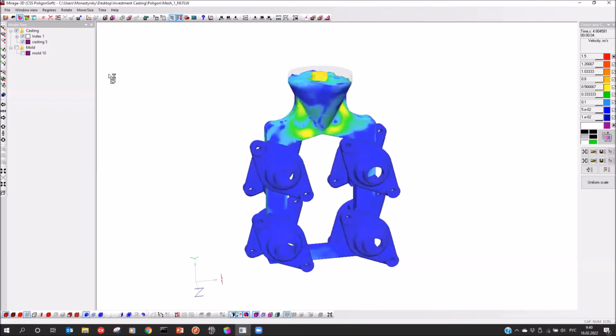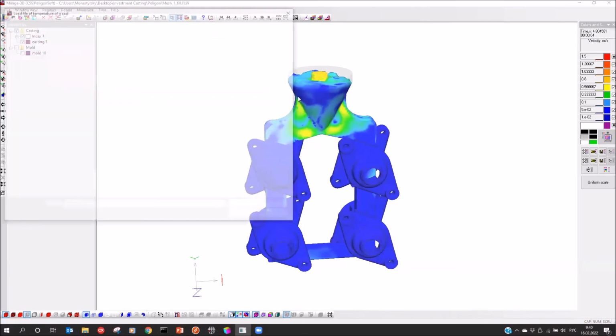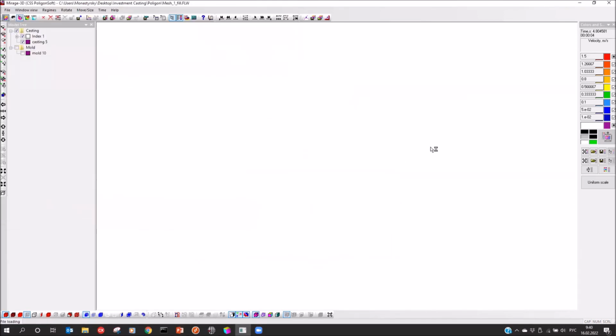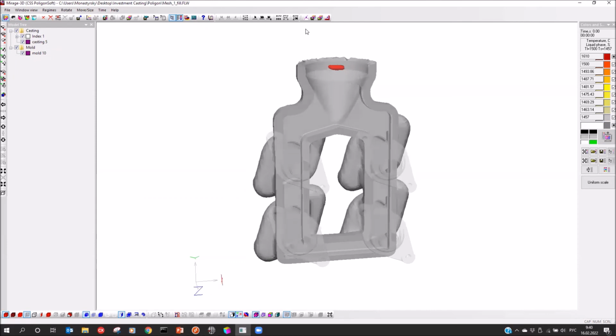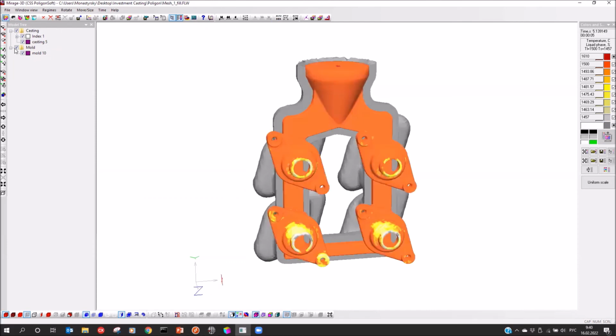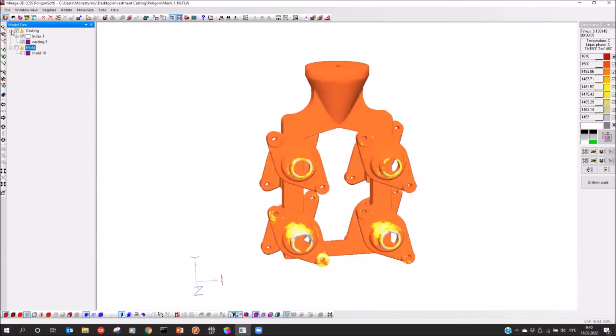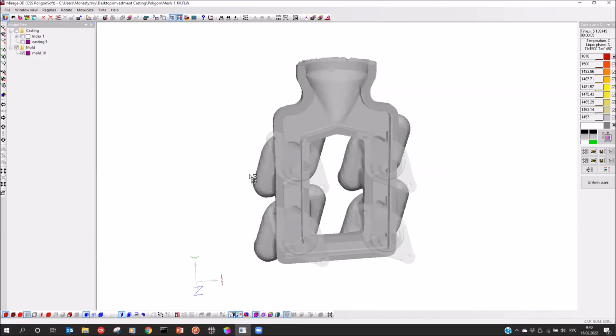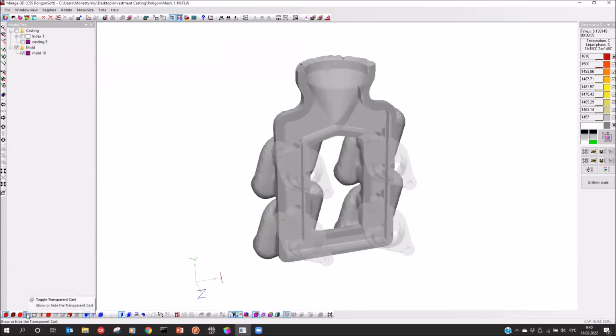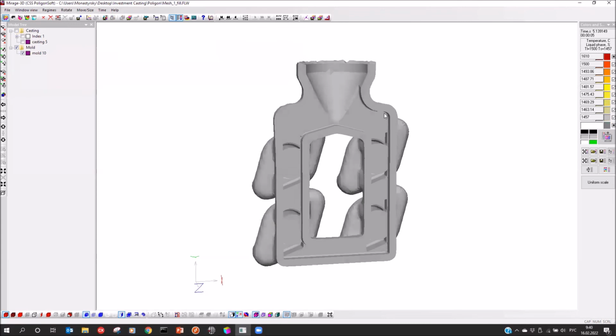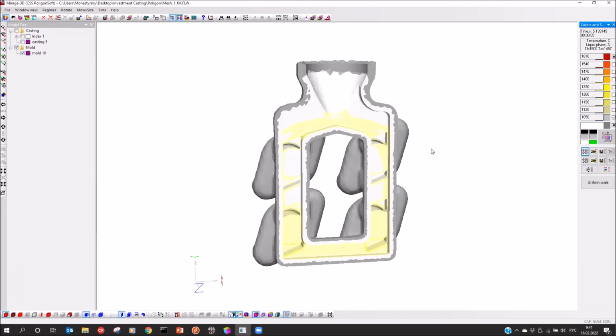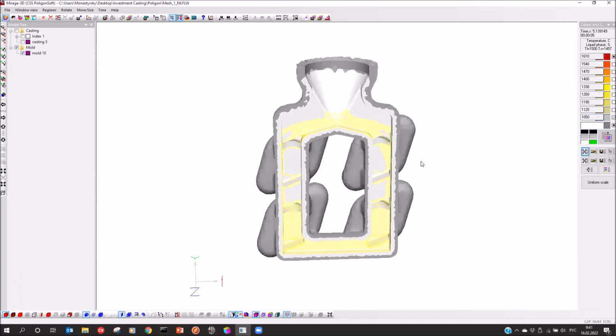And we can see the temperature field. I can load it. And I can go to the last step, for example, and we can see the temperature field on the mold. I think I need to correct my scale. I can correct the low temperature. And we will see mold heating during the filling.